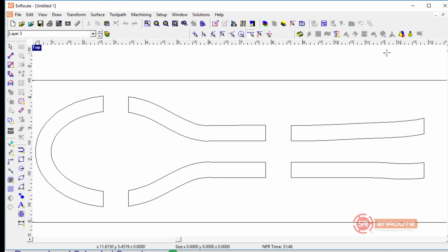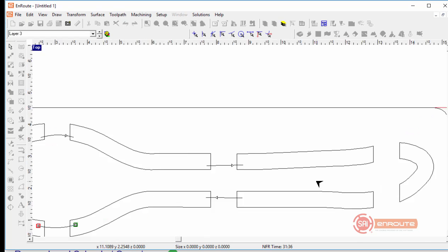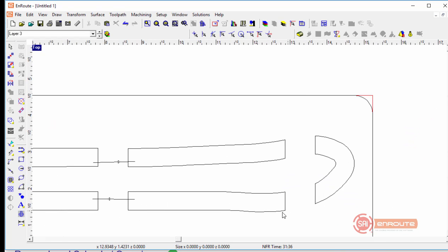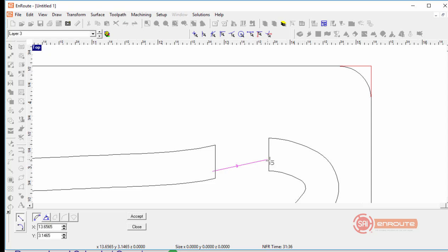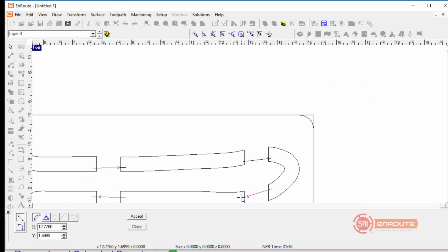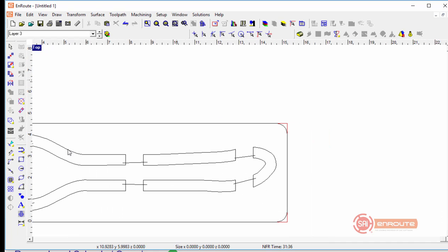All right, let's come here and let's draw some. I'm going to turn off my snaps and draw some 2D shapes here. Kind of going closer to the spoon than to the other edge. Now I can go to the point edit mode and go around a few of these and put a little radius on there to match the relief itself. This part was straight. And we need to do one more here. All right, so now we have this part.